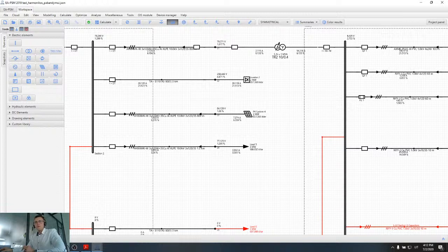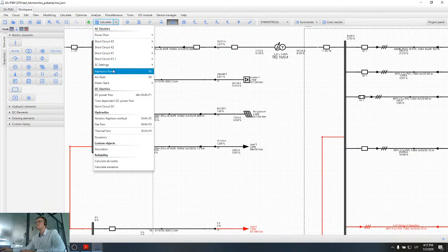Then there was a question from Kumar about why capacitors are installed with shunt reactors. Of course, they are installed in order to reduce resonance conditions. And of course the software evaluates harmonics by doing calculations based on the IEEE 519 standard.